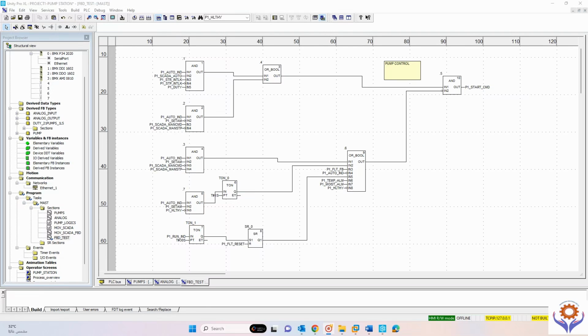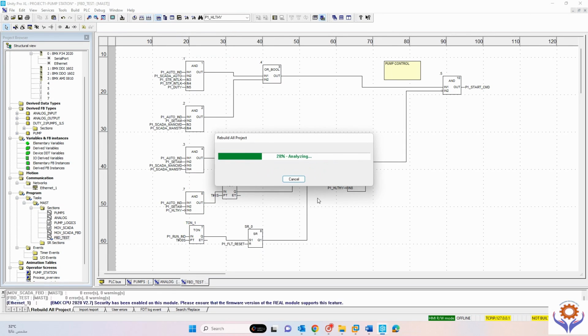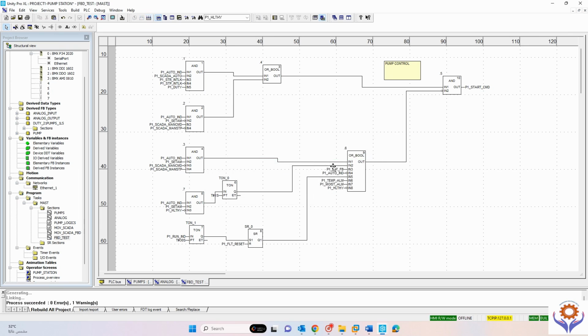So if you make this same function in your derived function block, it can be used, you can call this same function for many of the IOs. I will show you now. See, I will copy, save, and compile. See, there is no error currently. I will recompile and rebuild the application. See here, you cannot find any error, which means everything is okay.